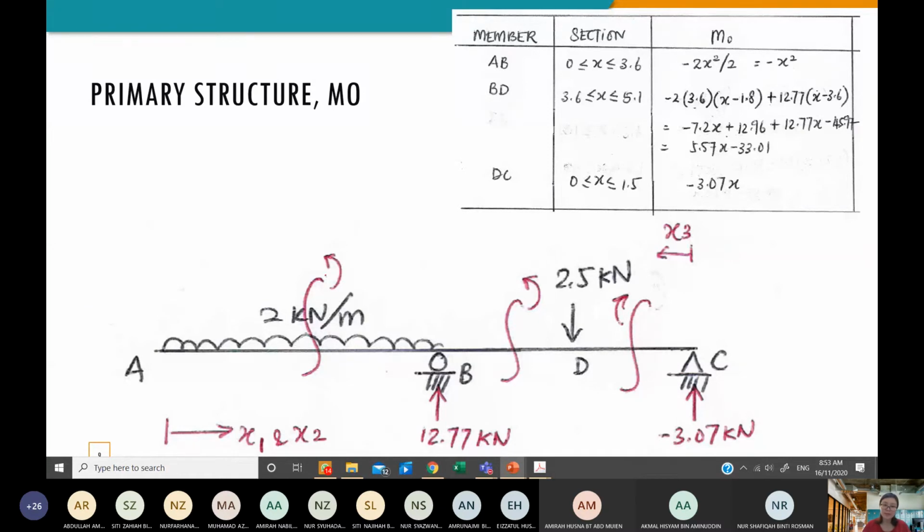Okay, let's say I have this cut section 1-1. My consideration is the left side. I put a square here. I'm considering the left side; the right side will not be under my consideration. So the loading on my left side is a UDL. I can represent this UDL as a resultant point load here, which is the rectangle of this load.